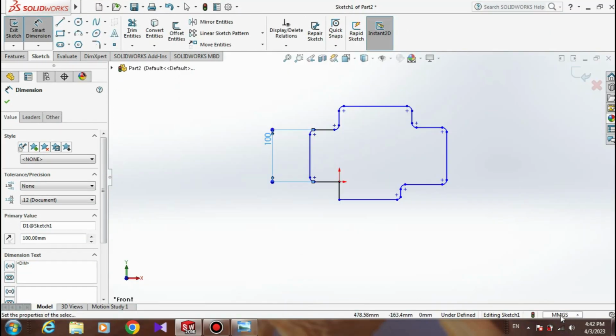One point about Solidworks here, you can see its unit system. So please choose the millimeter, millimeter gram second, mmgs. In European countries usually work with the IPS, inch pound second. So please be careful about that. It must be mmgs.